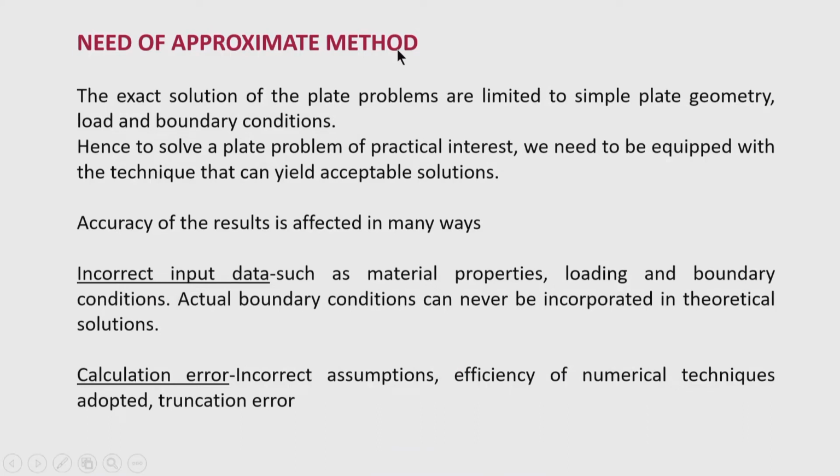Okay. So, first let us see why we need the approximate method. The exact solutions of plate problems are limited. Why is it limited? Because the deflection that we have found is valid for some cases with simple boundary conditions, that is the simply supported condition.